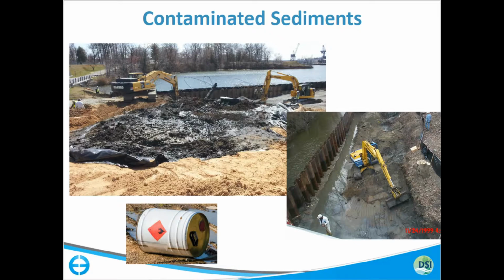you don't want to build the most complex model the very first time you build the model. We recommend that you build on essentially a series of building blocks. You start simple, hydrodynamics only, nothing else turned on, get that working. Then you add your density dependent components and start going multi-layer if you need to go multi-layer. Then you add on sediments, get sediments kind of nailed down. Then you move to the toxics, because every time you add one of these constituents, it adds computational time and data needs, and so it's really very helpful if you do it in a logical progression, using that process.